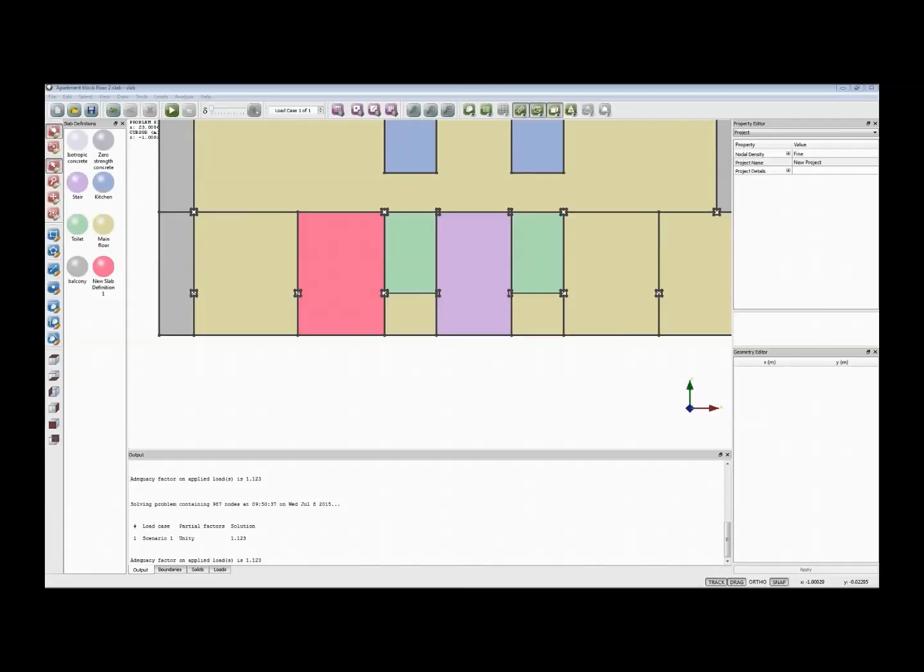Bending capacity is dependent on the type and orientation of the bars in the slab. Well, certainly you can change that. If you look in the property editor, or if I define a new material, you can certainly model orthotropic and also slabs with skew reinforcement.